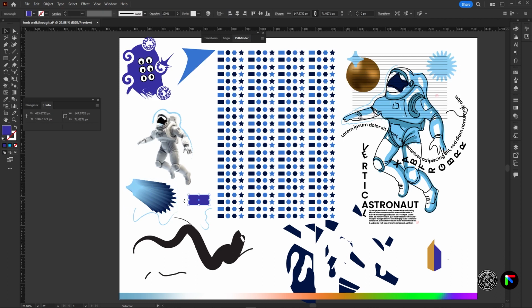And then I can also select this and this, and go back to my blend and do the same thing. Something for you to notice, a quick tip, is that the cursor indicator for the blend tool needs to change to a black color. As it is, it's a white colored box like you see. So once you hover over, you must make sure it changes to black before you click. That is when the blend will work, like so.